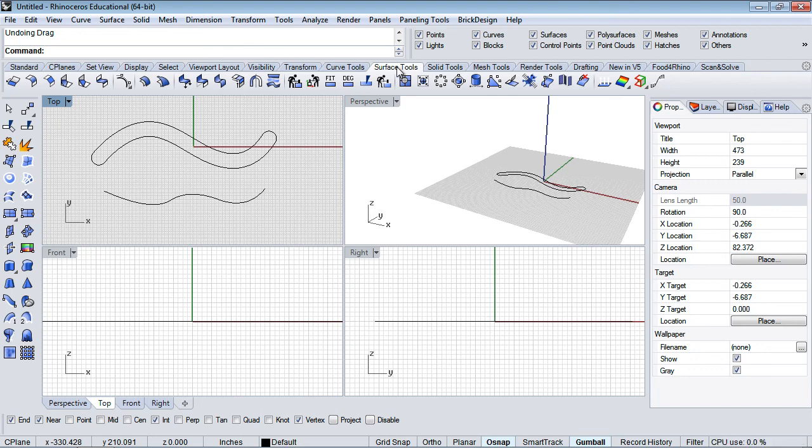Okay? When you join a bunch of surfaces together to create a solid, that could be called a polysurface, multiple surface, polysurface. Okay, so if you see that pop up on your screen, that's what that means. Okay, and a polysurface, if it's closed, is a solid. If it's missing something, missing a cap or a box end, then it's going to be a polysurface because it's not a solid. It doesn't hold water. Okay, does that make sense?